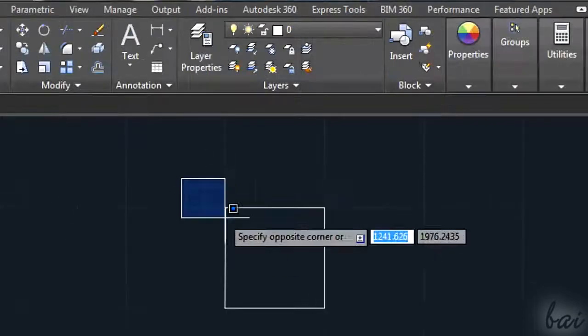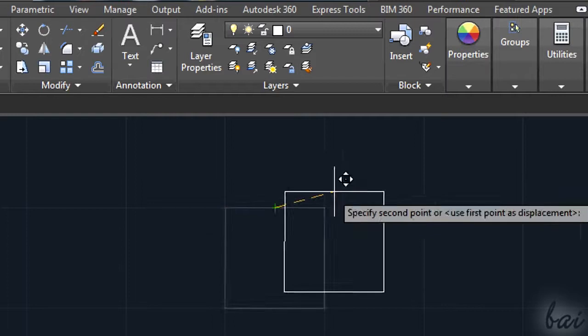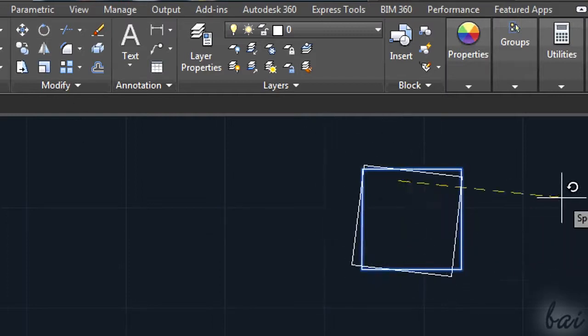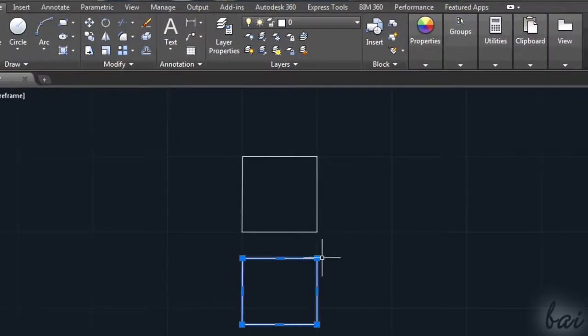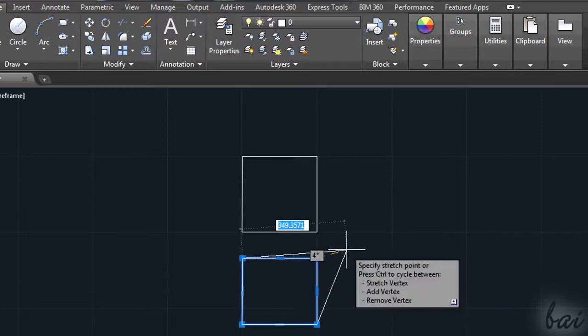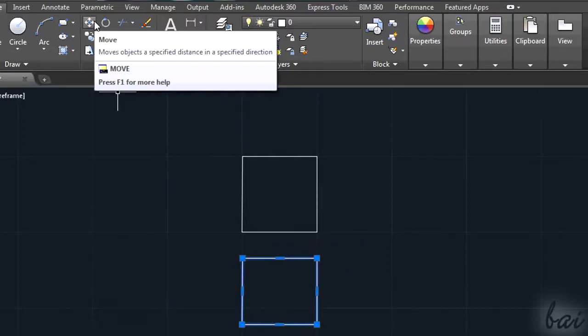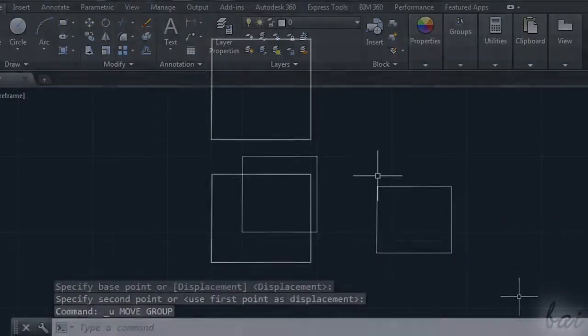And to modify your polygon made with the line tool, you need to use the Modify section on top, since you have to edit more objects at the same time. The polyline doesn't have this problem. The object is unique, so any editing is applied on the whole polyline. You will still need the Move tool to move the polyline around.